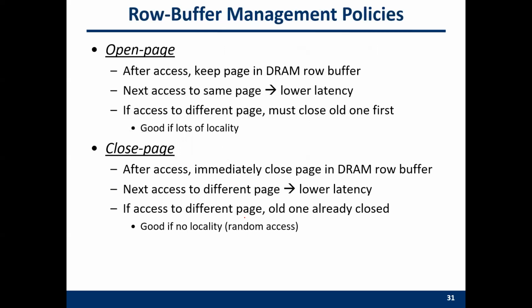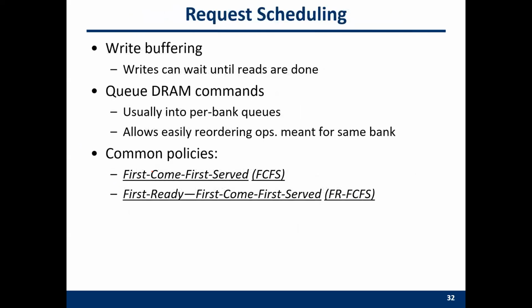So you can see that the memory controller is actually a very important component, especially nowadays, when every application will read a lot of data. Again, this is open page policy and closed page policy. It also has different scheduling policies, which is the so-called first come, first serve.